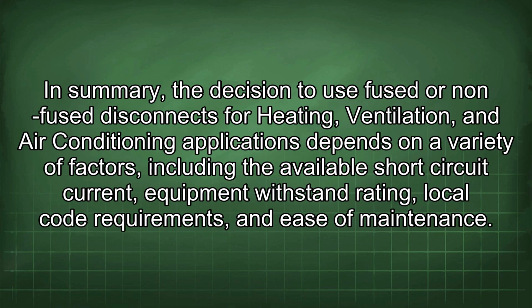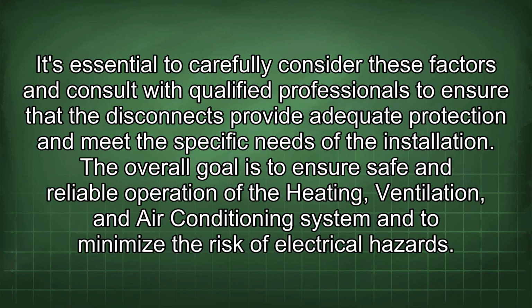In summary, the decision to use fused or non-fused disconnects for heating, ventilation, and air conditioning applications depends on a variety of factors, including the available short-circuit current, equipment withstand rating, local code requirements, and ease of maintenance. It's essential to carefully consider these factors and consult with qualified professionals to ensure that the disconnects provide adequate protection and meet the specific needs of the installation. The overall goal is to ensure safe and reliable operation of the heating, ventilation, and air conditioning system and to minimize the risk of electrical hazards.